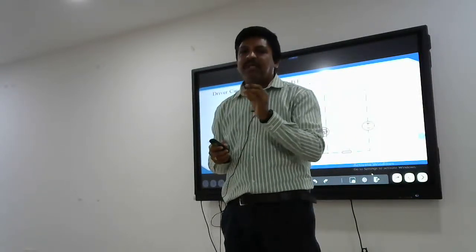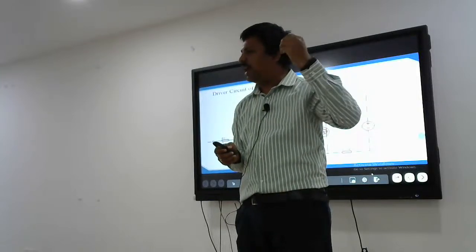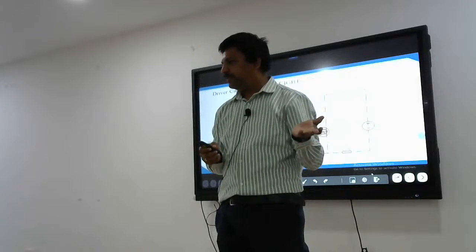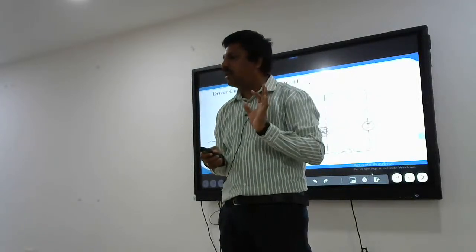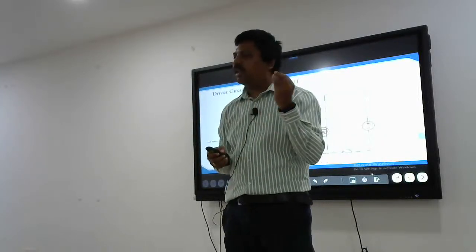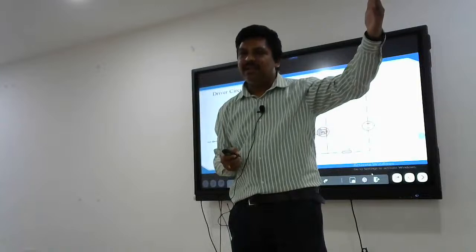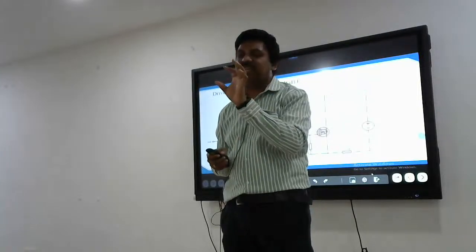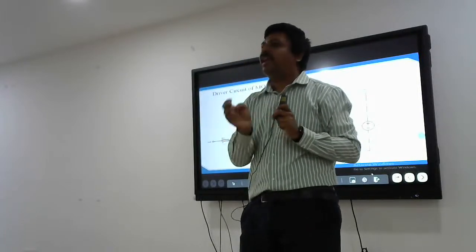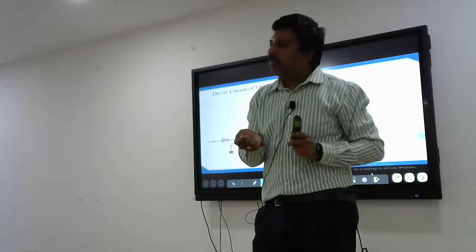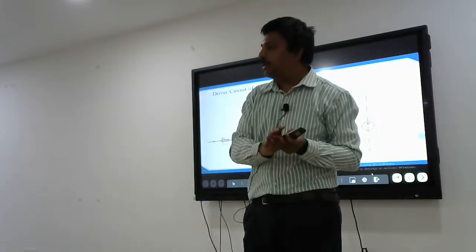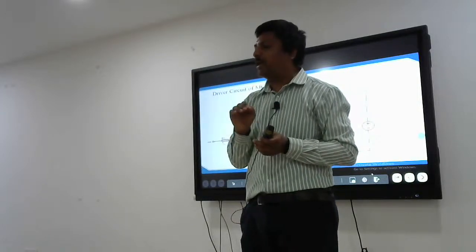If you simply want to control temperature, deciding on and off based on the temperature, a discrete 1 or 0 based on a set value, where if the temperature is greater than some value I turn on, otherwise turn off, then you need not take an Arduino and write code for that, or use an FPGA. You can use a simple operational amplifier, and that is called analog circuits. Using analog circuits we can make a control circuit, or using digital electronics we can also make a control circuit.